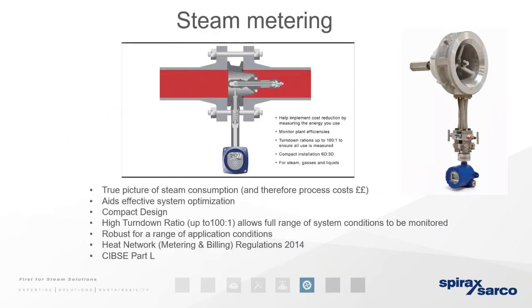When we have a look at steam metering, just as it is important to meter the steam leaving the boiler house, as we said a little bit earlier, it is also recommended that each individual process has its own dedicated meter, and that is for 3 reasons. My apologies. Firstly, process quality and control. Secondly, process efficiency and fault finding. And thirdly, custody and budgetary requirements.